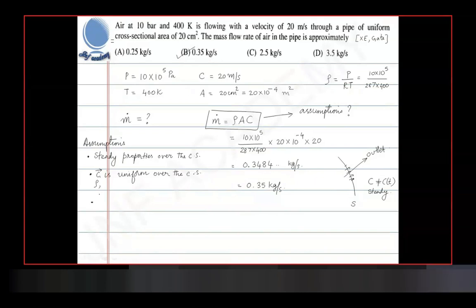I think the volume that's entering is same as the volume that's leaving. So there's no accumulation or any other losses in the middle. No. This equation has nothing to do with mass conservation. This is just the mass flow rate through a surface. It has nothing to do with the volume. You just have a surface, and what is the mass crossing that surface? Conservation has inlet and outlet, right? A volume will have inlet and outlet, sir. This is just for a surface. What is the mass entering or going through a surface?